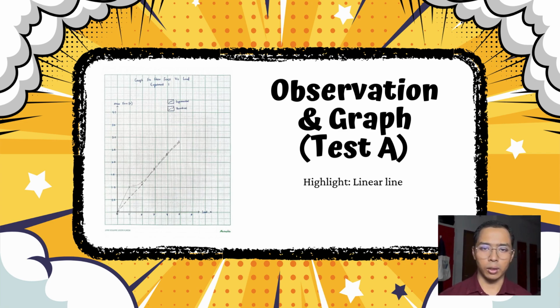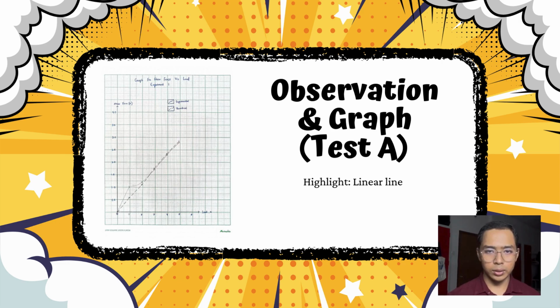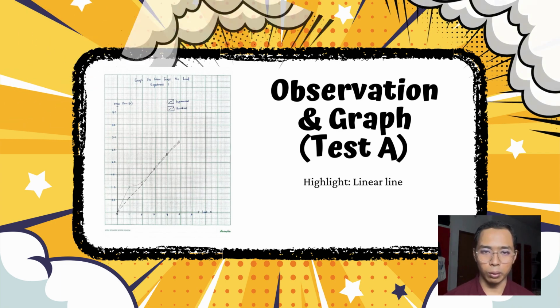In test A, shear force variation with increasing point load, we have obtained several data points. With the data, we have achieved this graph. As you can see, the data shows a linear line. It shows a directly proportional relationship between the load you put on the beam and the shear force at the cut, which means when the load is doubled, the shear force will also double.